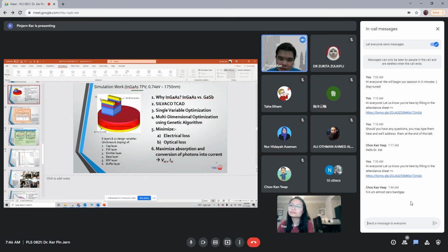when you have a metal contact on top, even in a solar cell it is the same thing. You want to minimize that so that you can optimize the photons falling onto your semiconductor. That is the first thing. But at the same time you do not want to lose the electrical part, because if you make your contact too small, your series resistance becomes too high and your fill factor is affected.